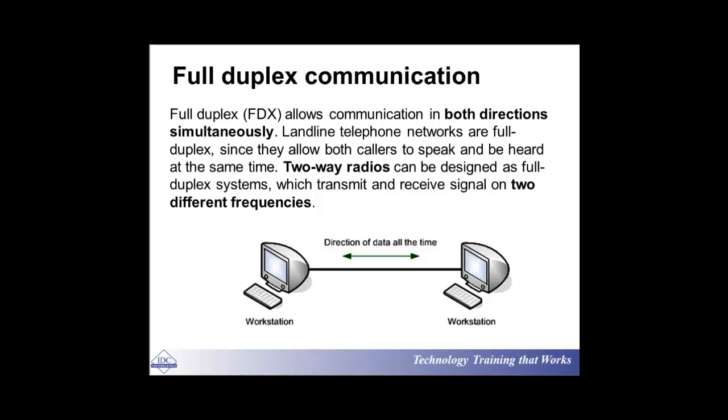But if it is full duplex, exactly like a telephone, you talk, the other person talks, and we can talk simultaneously. Even on the telephone, especially for remote calls, you sometimes notice that while you are talking the other person cannot talk, or while they are talking you cannot, and they will not hear you. That is more like half duplex. But if it is full duplex, the transmission and reception of the information can be done at the same time. It is more like walkie-talkies or two-way radios, for example.